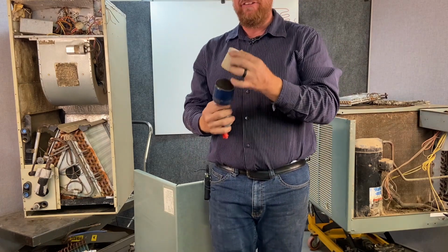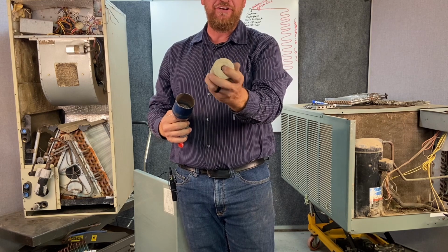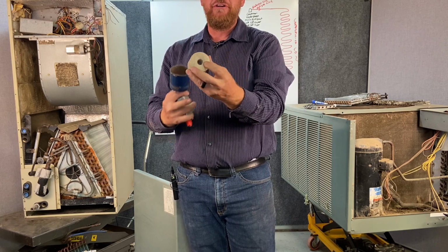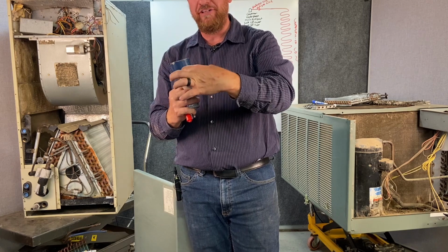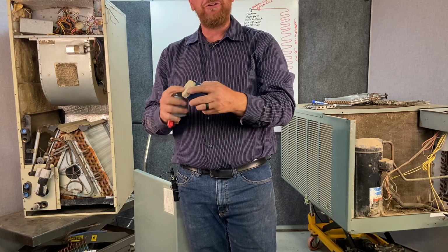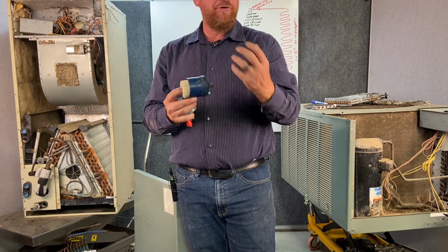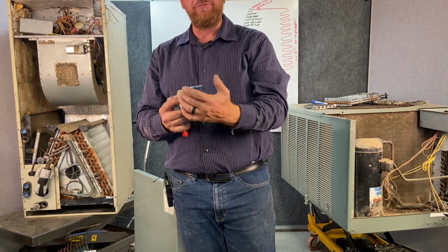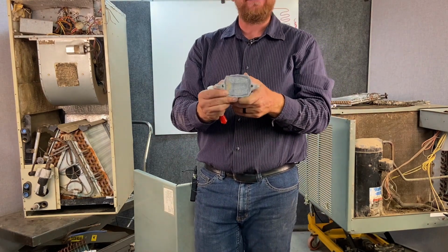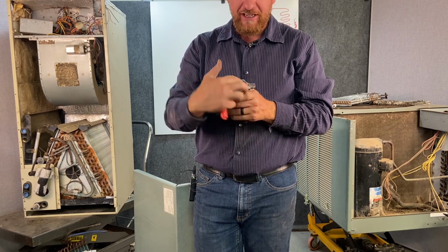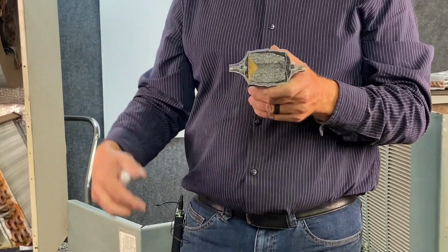There's many different kinds. This one's a solid desiccant type material, and it looks like a rock, but it still allows for refrigerant to flow through here. Refrigerant is going to flow on the outside section first, through this rock material and through the inside. And it filters the refrigerant and also pulls moisture out of the refrigerant. We don't want moisture in that system, but if there is, it'll pull moisture out. So another example of how they would look would be something like this. The refrigerant goes around that system, through the rock to the middle, and to the outside section.